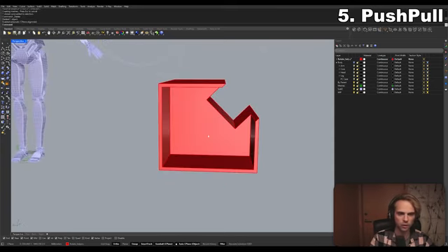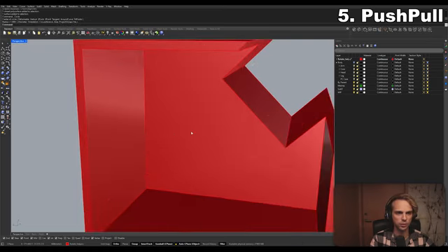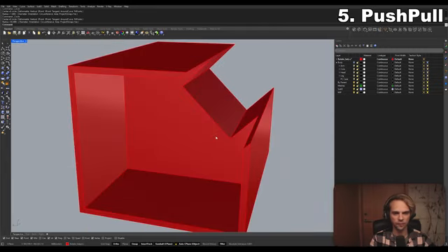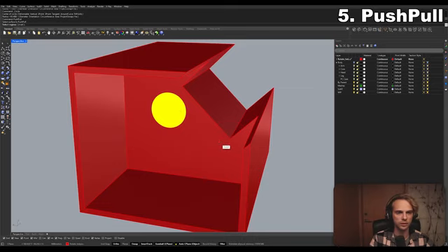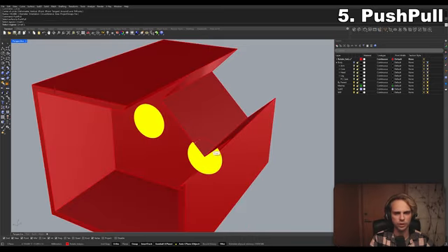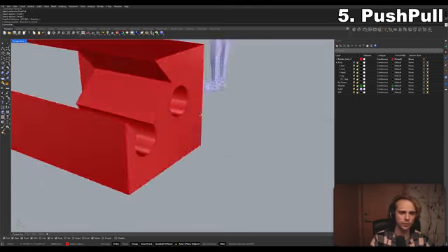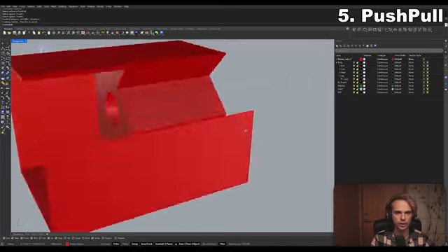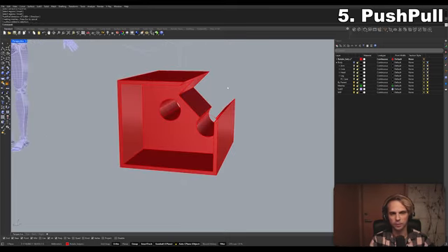Pair this up with auto C-plane, right? Where I can reposition the C-plane on here, and thus then I'm able to very easily draw circles and whatnot. Let's go for something like this. And then I push-pull again. Select inside of these regions. I believe you can select 2 of them at the same time. Yeah, absolutely you can. And you can easily push-pull through the whole shape, right? So that it actually booleans out a through hole, just like that. Such a convenient thing for 3D modeling purposes.